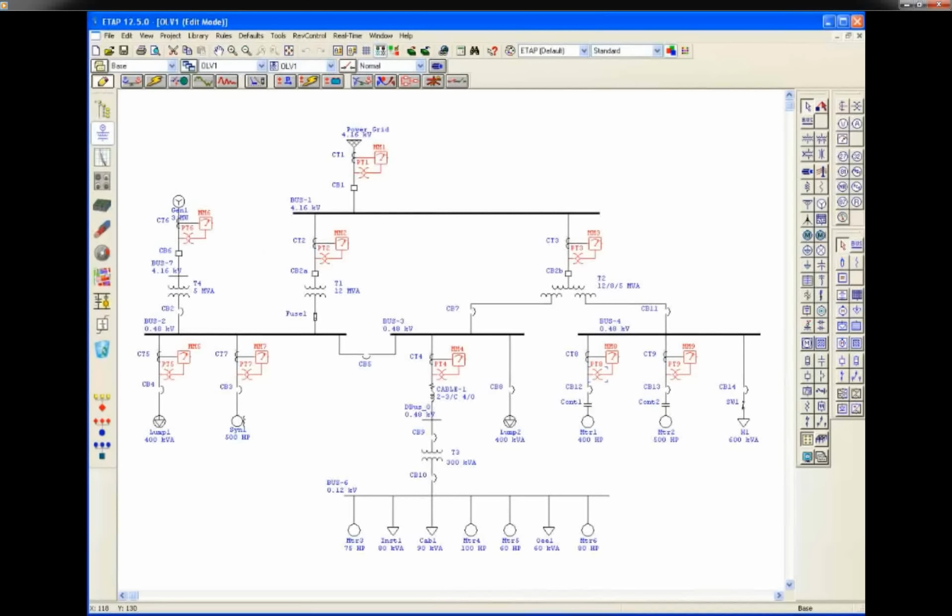Once the ETAP project has been set up with metering devices, we can then proceed to verify that the ETAP project data has been imported properly, and then we may perform ETAP real-time applications. We will show here that the imported SPEL project is able to run ETAP studies, such as a load flow analysis. By switching to load flow analysis, we can verify that the data from the published SPEL project file has been properly imported to the ETAP project. Now that the SPEL project is imported properly to ETAP, let's run load flow analysis.